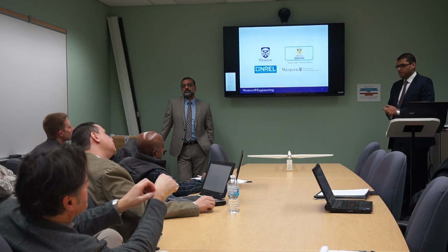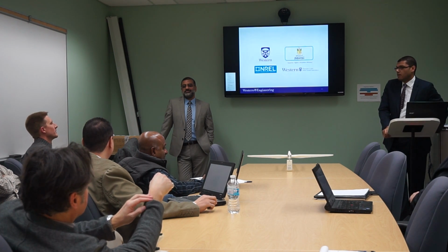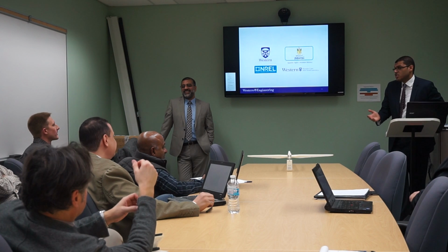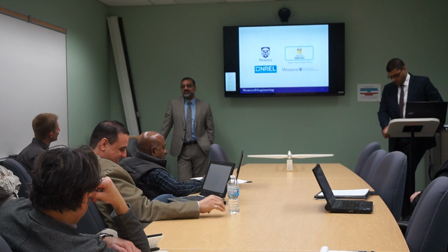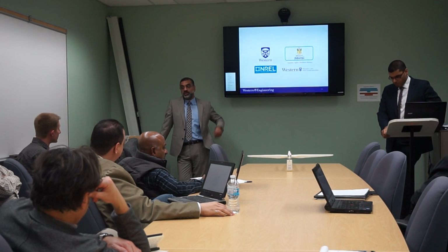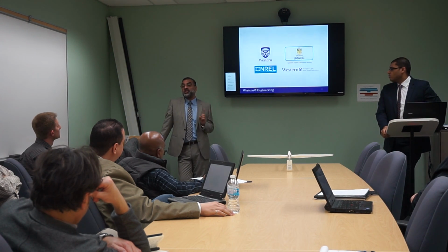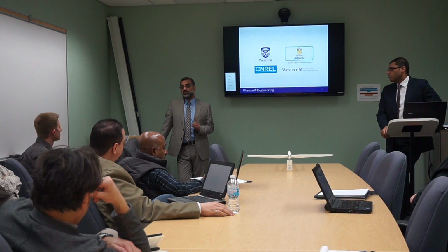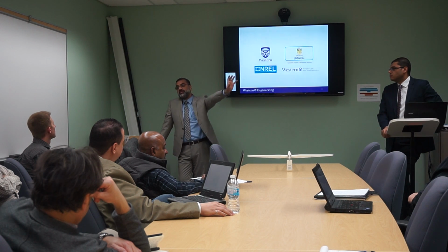Okay. So what I get out of that is you're pretty confident that it's going to cost less. Of course, it needs further calculation, but generally, yes. I have to interject on this one. I've done some study on the cost of installing piles for offshore structures, not wind turbines. And the cost of installing a 6 meter pipe is $17 million. The vast majority of this is not the material. It is the rental for the barge that will drive it in. You can use a smaller hammer, smaller barge. The cost goes from $70 million down to $10 million. That's where the savings is.